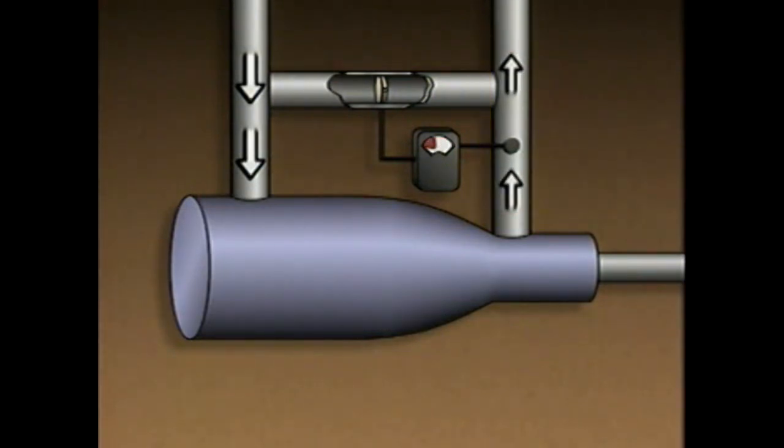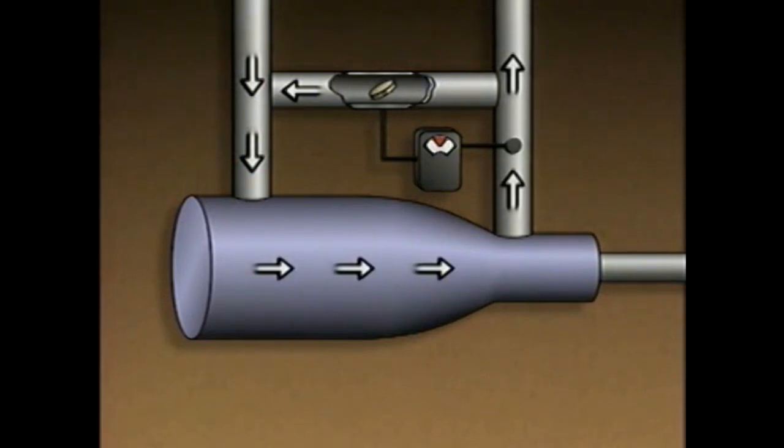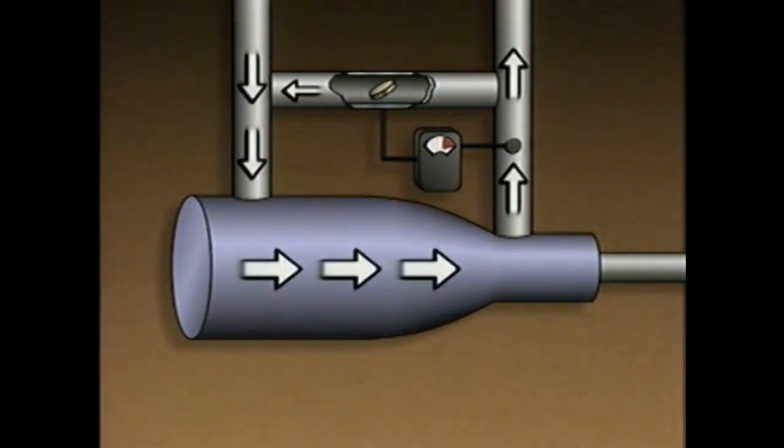When low demand causes the gas flow rate to approach the surge point, the flow sensor sends a signal to the flow controller. The controller then opens the recirculation valve and routes a portion of the discharge gas flow back into the suction piping. When a portion of the discharge gas flow is routed back into the suction piping, the gas flow through the compressor increases and it stays above the surge point. When demand increases, gas flow through the compressor also increases. When the gas flow is high enough to prevent surge, the flow controller closes the recirculation valve.